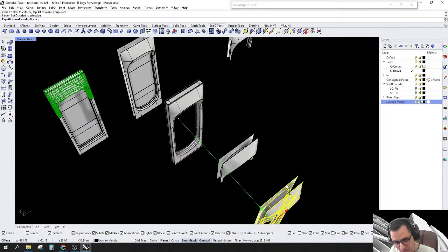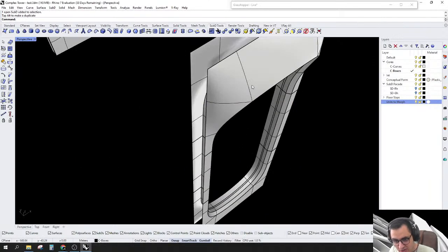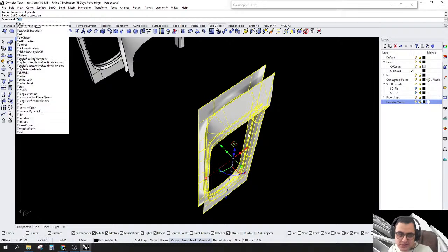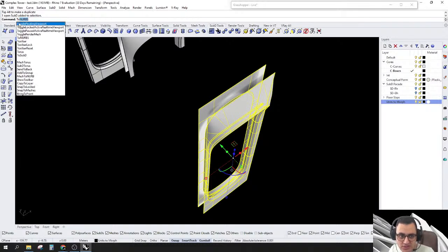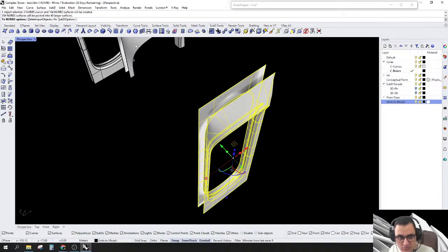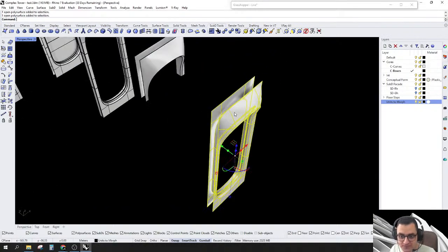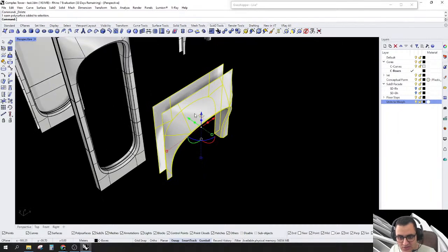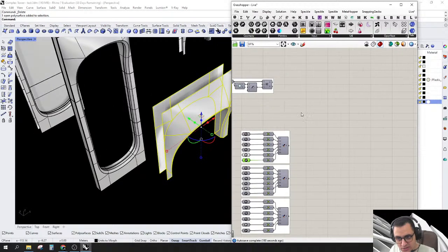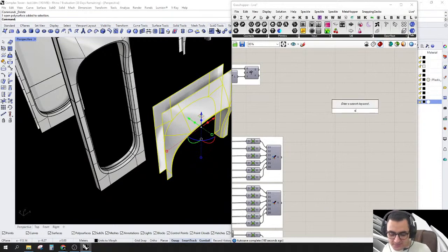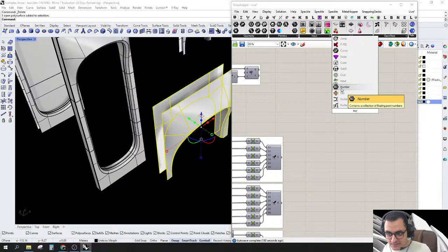If you want to transform a sub D into a B-rep, just click on it and say To NURBS. You will see it in here, and you want to delete the input, and there are some sub D options. I don't care about them for now. If you want to delete the input or not, for now let's say yes. I don't want the input, and you will transform that into a NURBS surface. So basically what I did in here is just input this. Let's say B-rep.